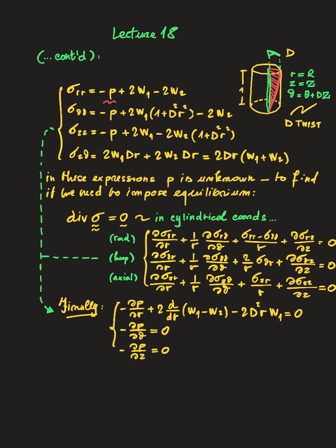So you see, there is a strong advantage: in the end things get very mild. I only want to make a little remark here. If you notice, I didn't use a partial derivative, but only an exact derivative. The reason is that if you compute the invariants I1 and I2 in this problem, you will discover that the two invariants of the tensor B are both equal to 3 plus d squared r squared.